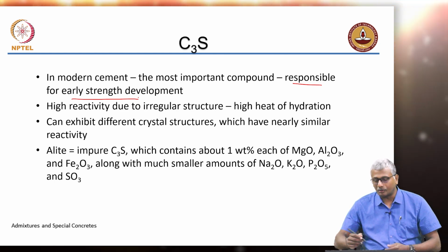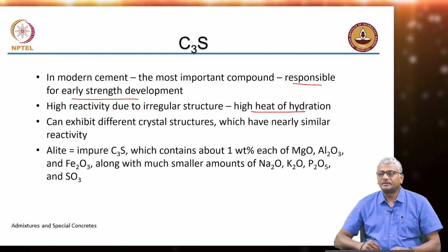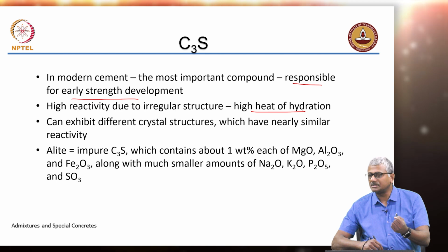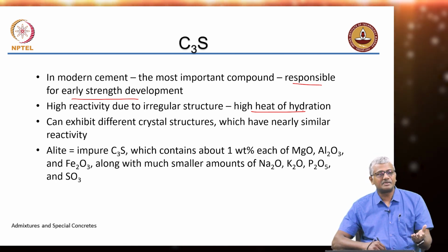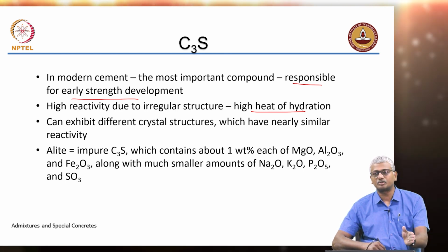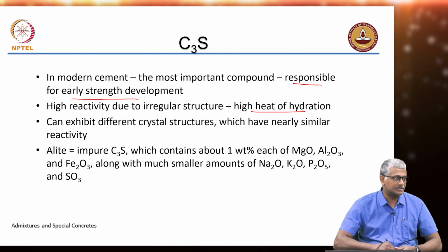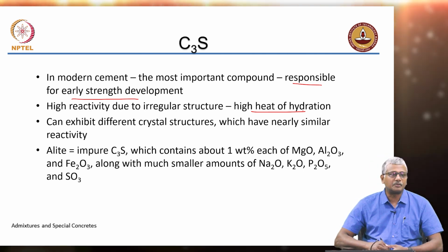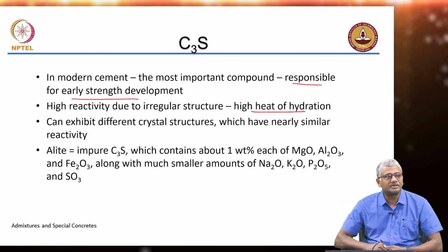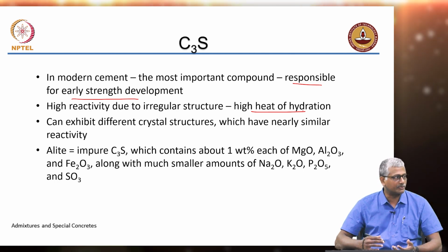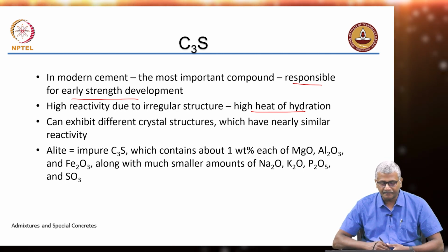And high reactivity also means it has a high heat of hydration. What do we mean by heat of hydration? It is the heat liberated when cement reacts with water. So, cement is composed of different compounds, and the heat that is liberated when cement reacts depends on heat liberation of individual compounds. The compounds that react faster liberate a lot more heat. You might have seen this with lime, right? Slaking of lime. We typically add water to calcium oxide. There is a massive heat evolution from that process. Same thing, even here in cement there is an exothermic process which releases heat.